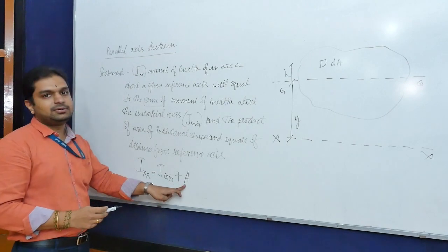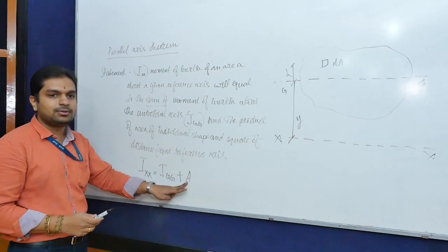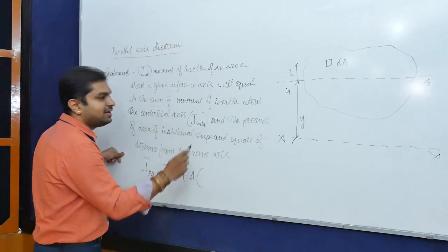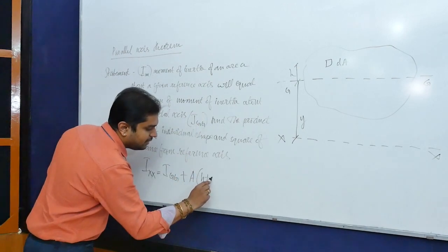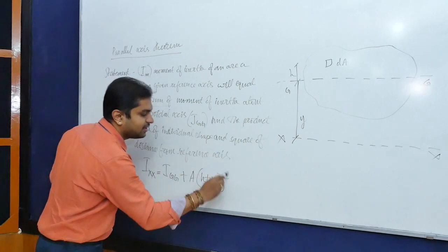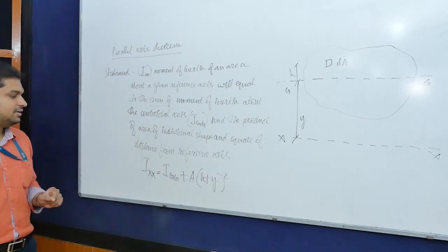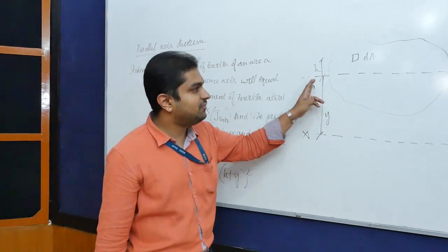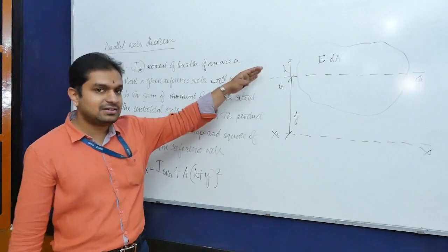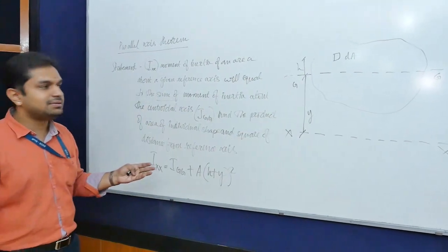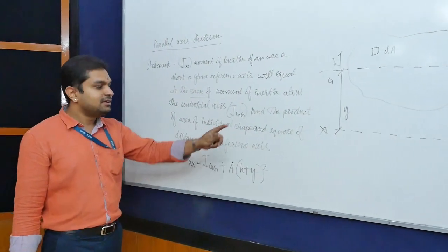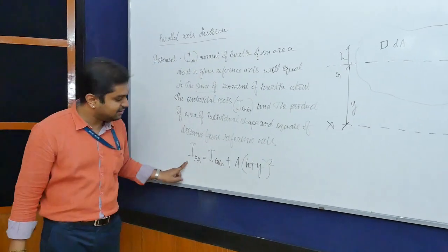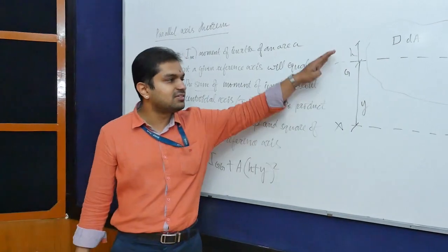This is important because whenever there is a complex shape, in order to reduce the complexity, we divide it into areas of known dimensions and shapes. And this perpendicular distance here will be equal to h plus y, the whole square. So that is the statement of the parallel axis theorem. In general, we first establish the centroidal axis and then find the distance. We will follow with a derivation to obtain this; this statement is with reference to the diagram given here.